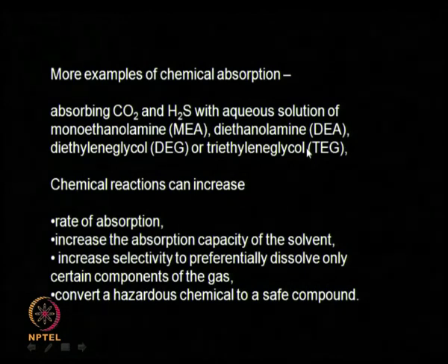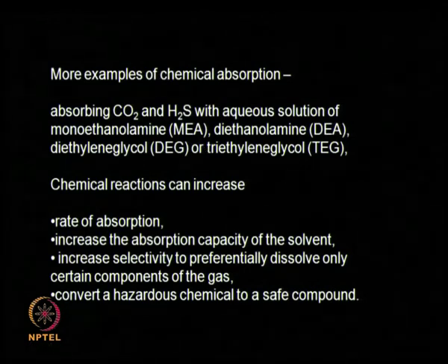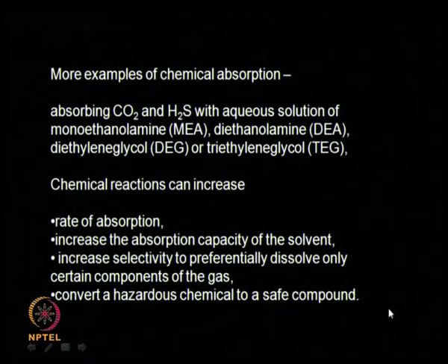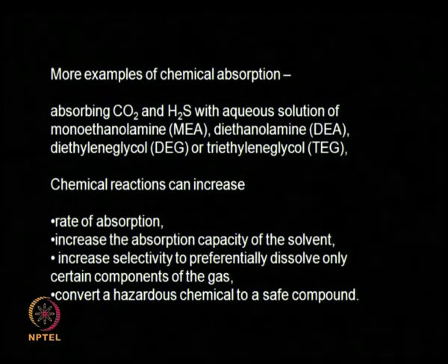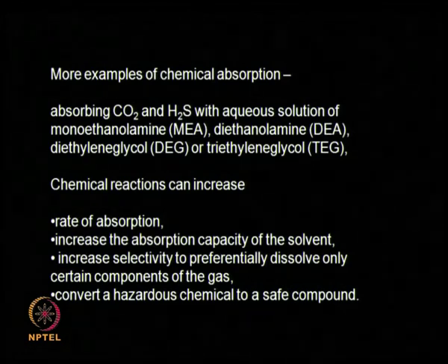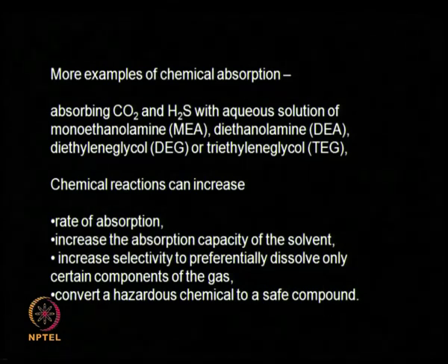So what is the advantage? The rate of absorption increases, it increases the absorption capacity, we can selectively or preferentially dissolve only some components, we can even convert hazardous chemicals to safe compound. So that is the advantage of doing chemical absorption. But the main disadvantage is the liquid which we are using gets consumed. For example, if I am using sodium hydroxide, for absorbing carbon dioxide, it has become sodium bicarbonate.